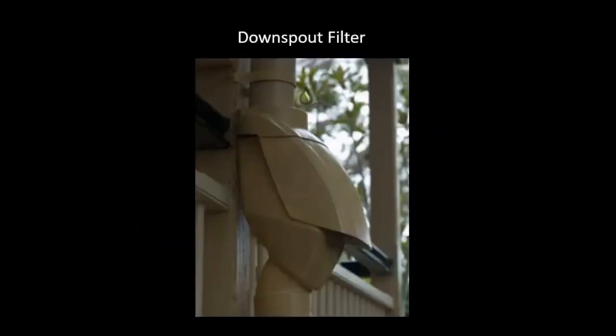Now, you can put leaf guards, gutter guards, on the gutters. The best ones that I have found are stainless steel, and they're some that you could get at Costco. And then there are also some with bigger holes if the volume of water is a problem, from Lowe's or Home Depot. But if you don't have any guards on your gutters, you're going to get things building up in the gutter. So my preference is to have screens on the gutters.